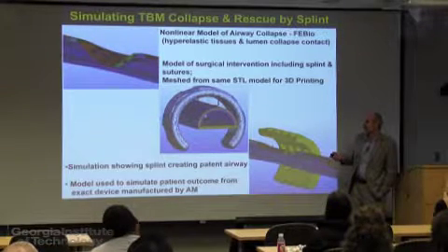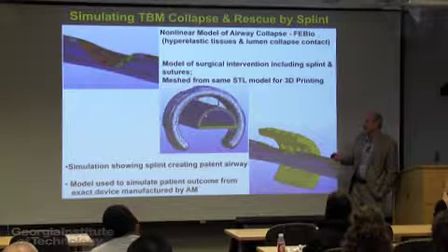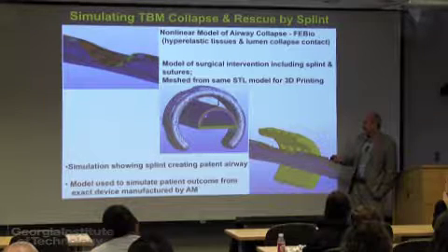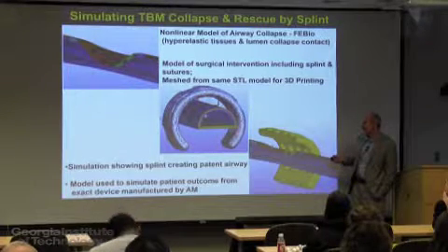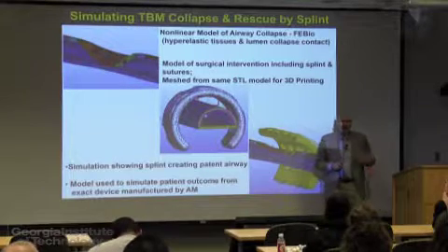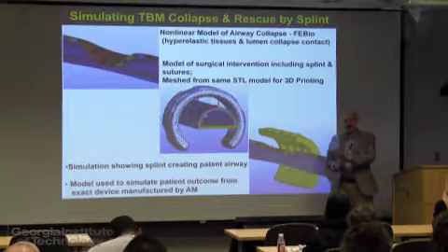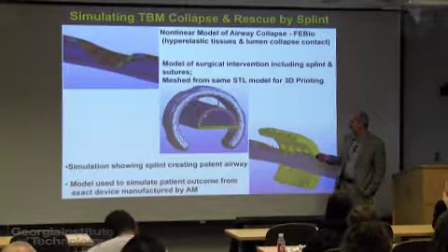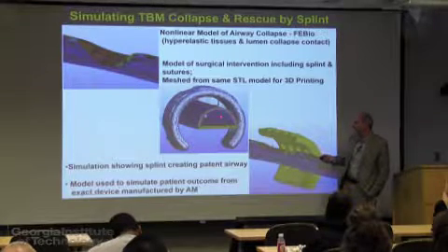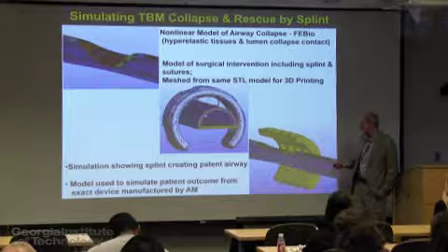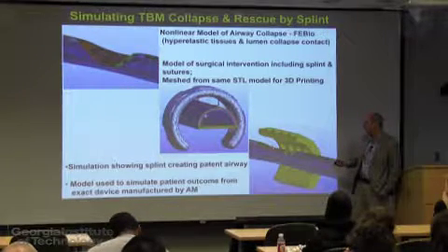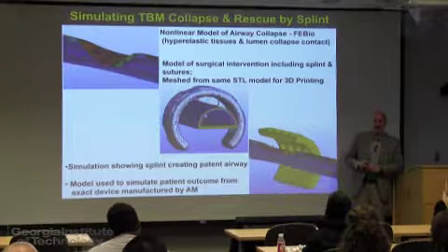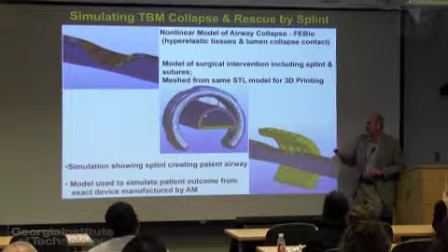We can actually simulate, due to reduction of tracheal properties in this finite element simulation, how the airway collapses. And then, because of this file format, this is the STL format that we use to design the device, we use that file format not only for the 3D printing, but we use it as a basis for generating simulations of the device. We can implant the device, simulate the suturing of the device to the airway, and show that the device will maintain patency of the airway once the airway is sutured into the device. So we can now implement patient-based not only design, but simulations into creating devices.